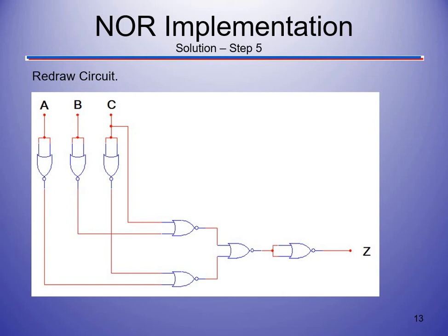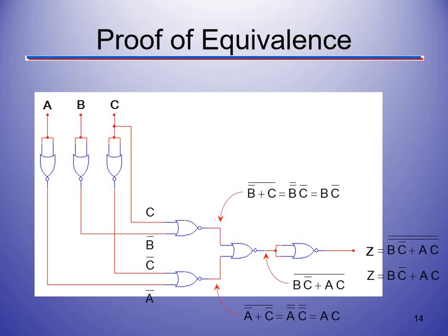So it's still saving us money, still cost effective, but not nearly as cost effective as the NAND is compared to the NOR. And like I said before, this is something I want you to make sure that you're working on, that you are drawing all of these and you are writing the outputs of the gates in every single scenario. It will really help you through this.